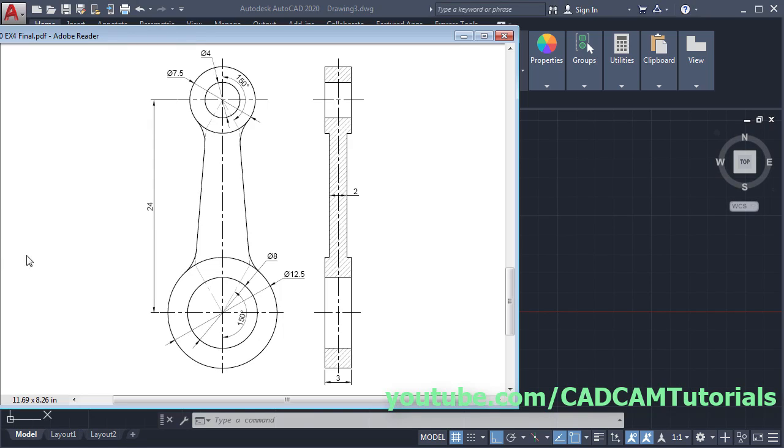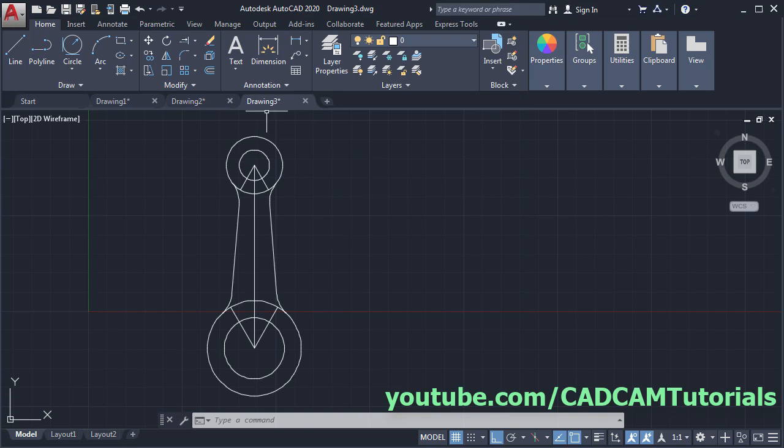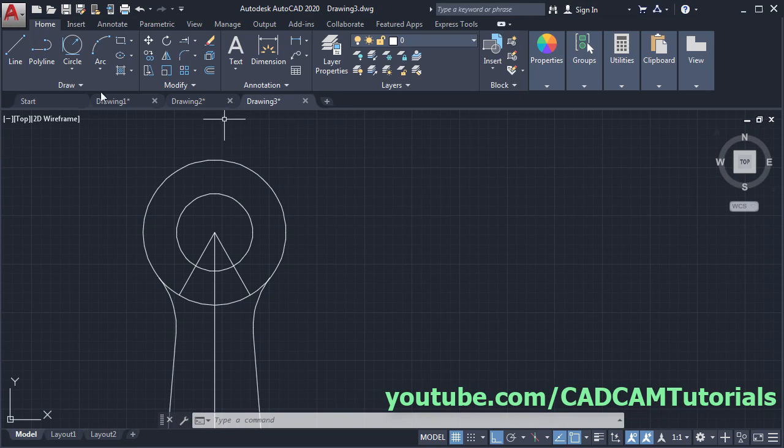Then next is to create this section view. Now this width is 2 inch and this is 3 inches. Zoom here, click on line, take your cursor to this quadrant point, take it away and click. Then take it on the right side, give the width of 3, enter.